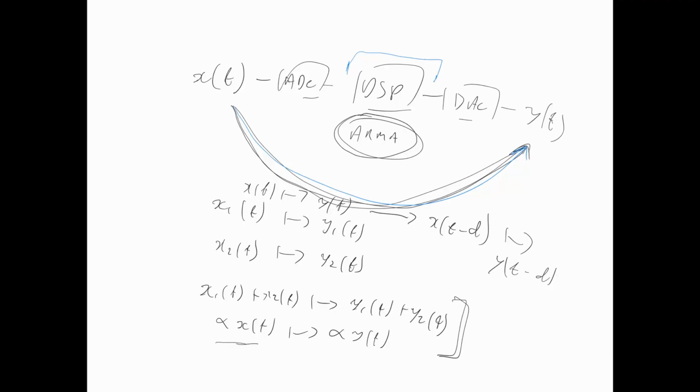If we put a square wave into a system, we are probably not going to get out a square wave. But if we put a sinusoid in, and it's an LTI system, we will get a sinusoid out of the same frequency. Very simple behavior. Because it's an LTI system, if we know what it does to sinusoids, then we know what it does to linear combinations of sinusoids, and we know what it does to delayed versions of linear combinations of sinusoids, and so forth. And it turns out that essentially any signal we care about can be represented by a sum of sinusoids. And that's why frequency and LTI systems go hand in hand.